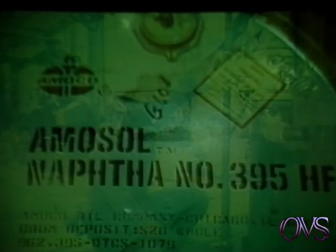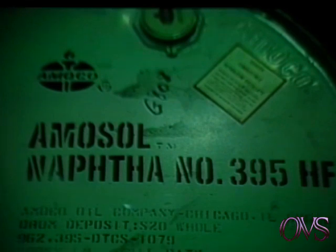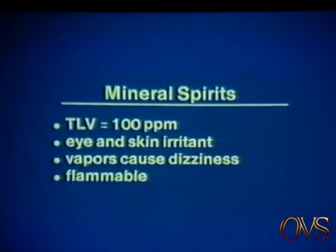On occasion, we ship mineral spirits in our pipelines. Mineral spirits is a petroleum distillate, and it may contain a small amount of benzene. The threshold limit value for mineral spirits is 100 parts per million. Health effects of exposure may include eye irritation, skin irritation, and dermatitis on repeated or prolonged contact. Breathing mineral spirits vapors in high concentrations can cause dizziness, headache, nausea, and vomiting.